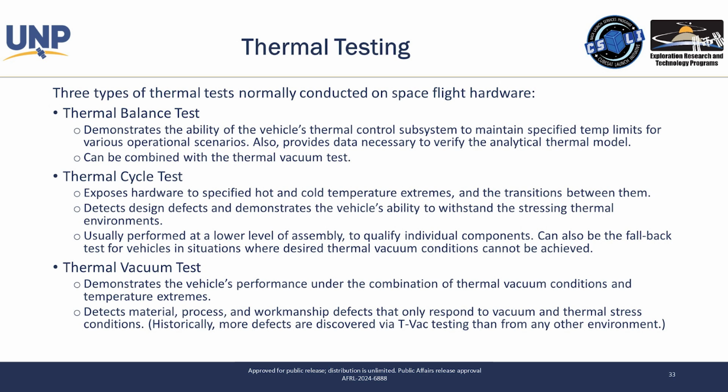And so you'll typically do that towards the end after vibration testing. And that's kind of your last final, like, oh man, okay, if we pass this, we're good. But that's why I said plan for disassembly, because if you find something that late, you need to be able to go fix it and get back through all of these tests and prove that you are good.